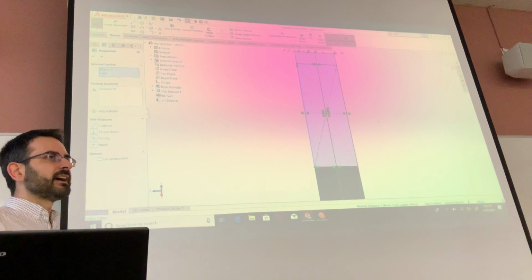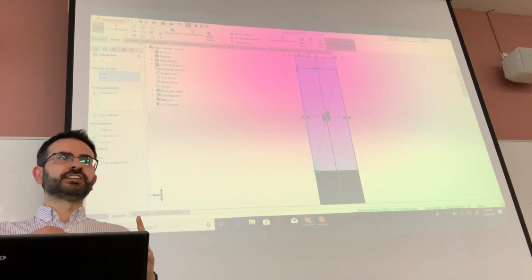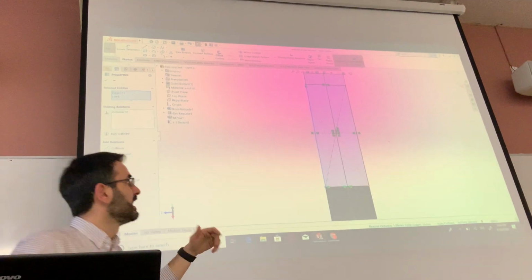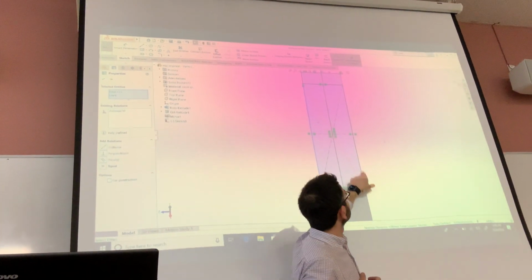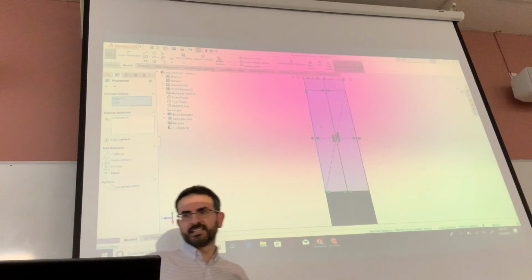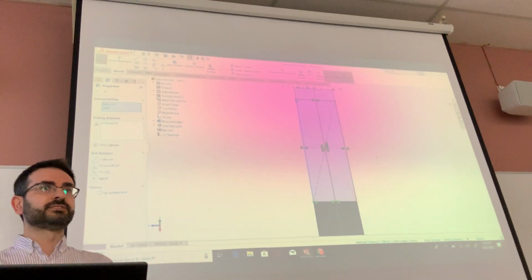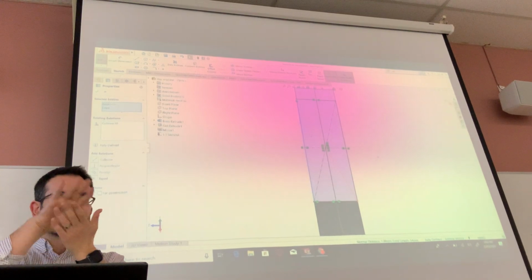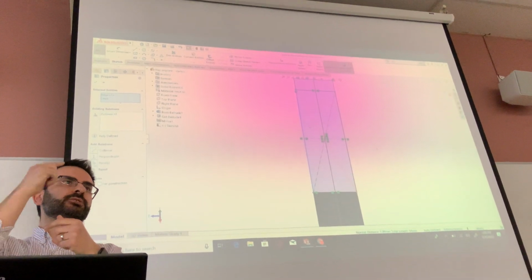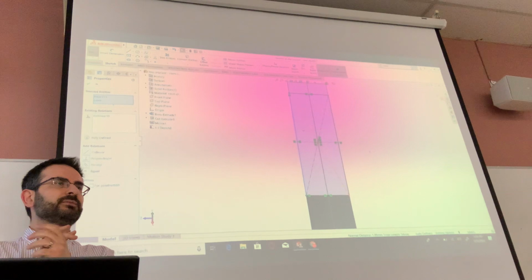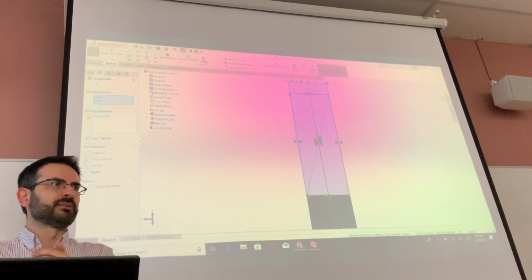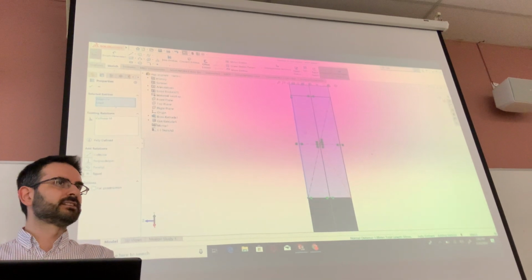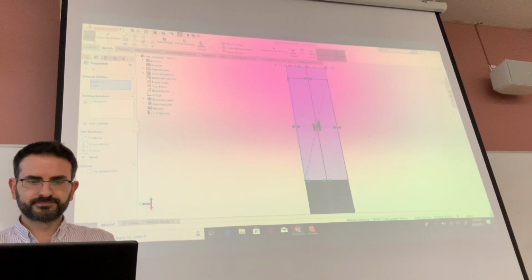Now, if I had done the filleting of the geometry of the stem, I'd have the rounded corners here on the four sides. And so I'm gonna round the corners of these two, which means that in the final volume there will be some kind of strange discontinuity, but it's just because I haven't filleted the stem. So if you go later and fillet the stem, then you get a smoother connection.